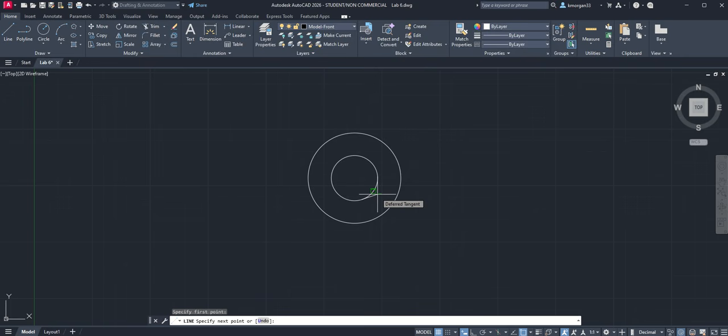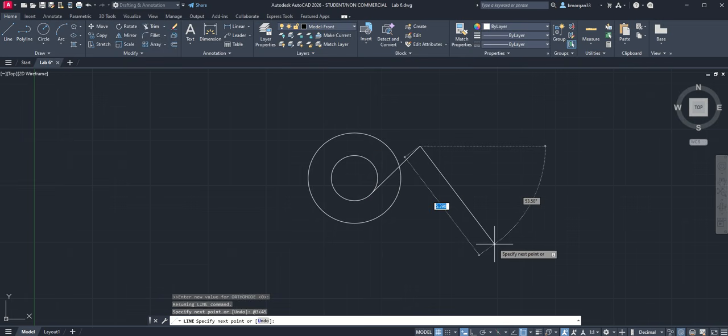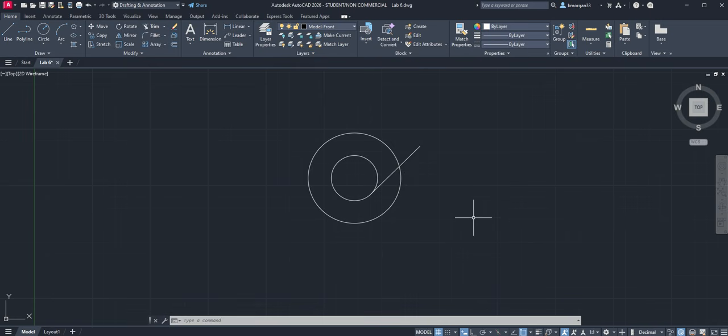And right now, let's type 3, and then we will call our angle, which is the less than symbol, and then we go 45-degree angle. So make sure you enter that. Once you enter that, you will get a line, 3 less than 45, an angle that has been drawn there for you, so you can either press Space, Escape, or Enter. Okay, so now we finished this.